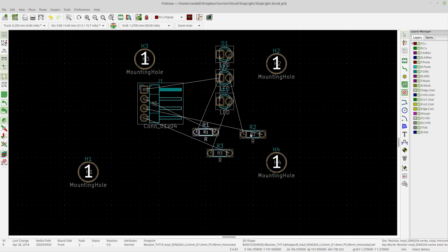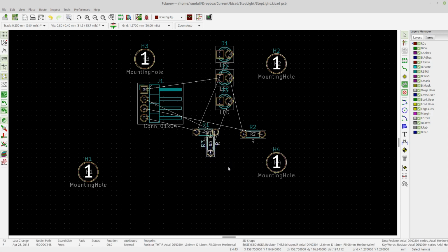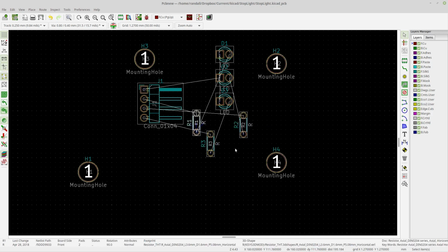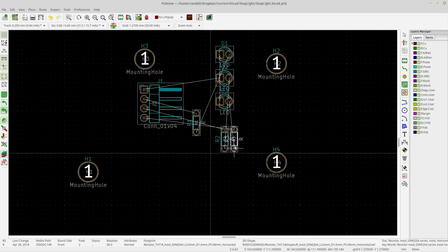And now the first thing is I want to orient these resistors vertically, so I'm going to click on them, and I'm going to box select. If you click and drag, you get a box select, and I'm just going to hit rotate, and that's good, and rotate, and that's good, and rotate. So those are how I want them, and then we're going to bunch them up right in the middle here. So I'm just clicking, and then M for move.